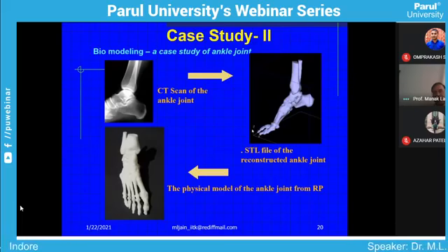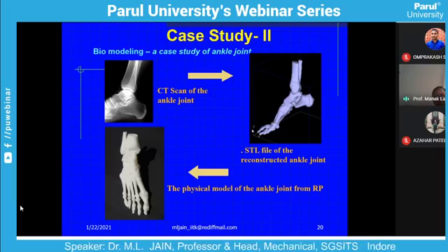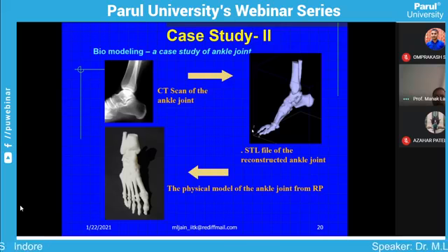For conversion of CAD file to manufacturing file, the conventional or the old concept name of that particular file is known as stereolithography, right? STL, stereolithography. So you convert that CAD solid model into a stereolithography file, which is a manufacturing file, and put this manufacturing file into a 3D printer. All globe 3D printers are welcoming only stereolithography file.